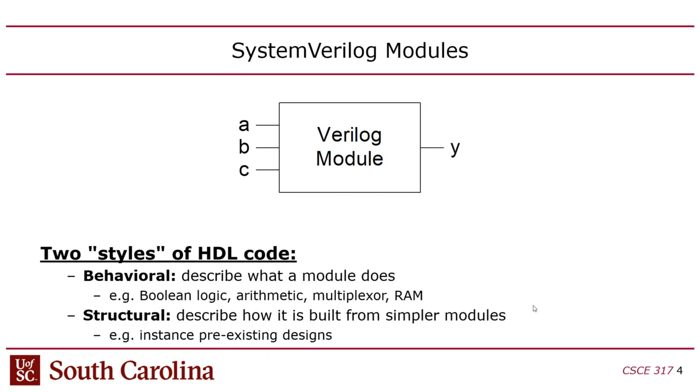If you randomly went to GitHub and opened any Verilog code, I would guess there'd be a 99% chance that code would just be structural. You'd be looking at basically a schematic, because the behavioral code is reserved for the primitives, the low-level components, because everything is built on top of those.